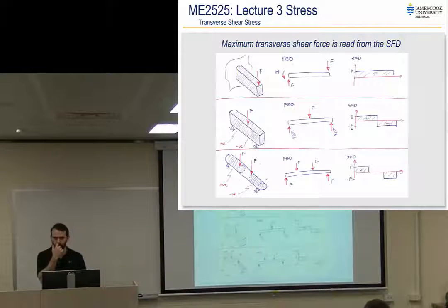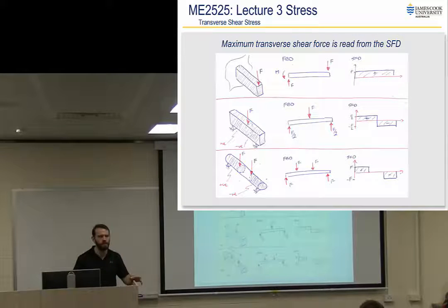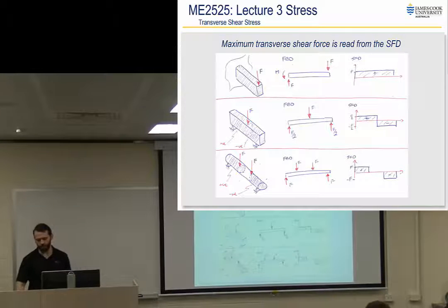All right, so that's the first kind of test. The first, all right, where's our maximum force? Now we need to think about, all right, what does the stress distribution look like throughout the cross section in any of those maximum areas? And in some circumstances, not the maximum areas as well. If you've got lesser values, they might add up to a larger bending stress somewhere else. So you need to be able to calculate the maximum stress anywhere, or the value of stress anywhere. But we'll look at the maximum for this example.